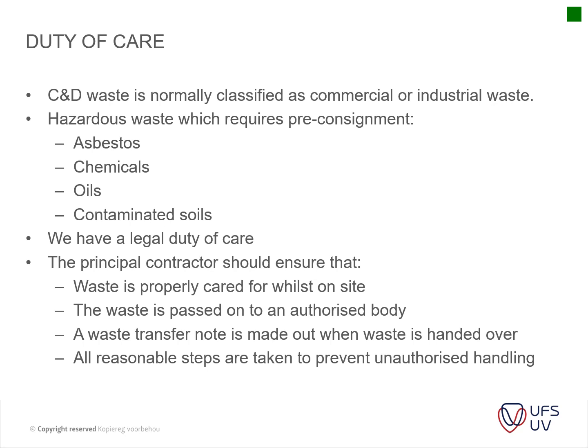Okay, duty of care. Construction and demolition waste is normally classified as commercial or industrial waste. Hazardous waste, which requires consignment, is for instance your asbestos, chemicals, oils, contaminated soils, and so on. I've worked on one project where we had to take off asbestos. It's a schlep. There's only like 4 contractors in the country that do it, so it's highly specialized work, and they usually ask a lot of money for it.